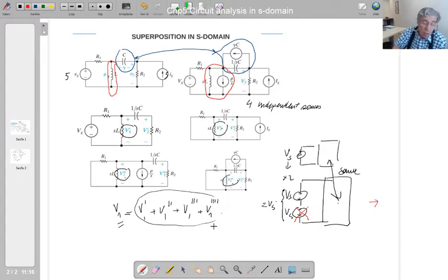The second time, according to the superposition theorem, I am going to keep this independent source in and remove, or deactivate, this one. So this is in, that's out, but it's going to be the same circuit as this, isn't it? So whatever you found previously for the red one is going to be found for this new one here.